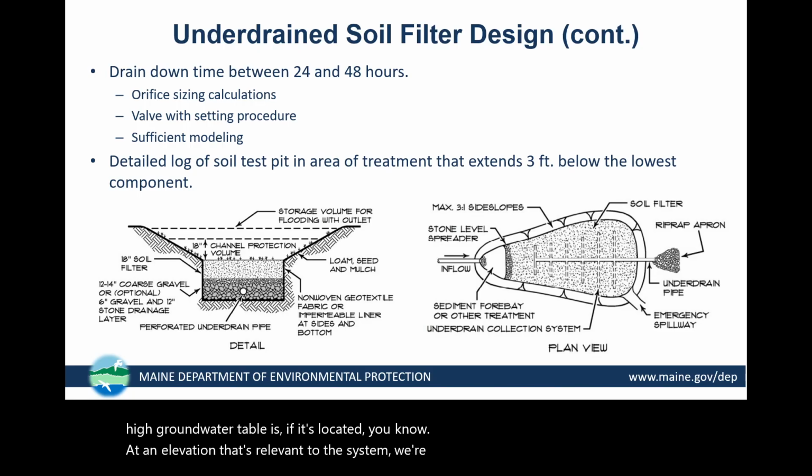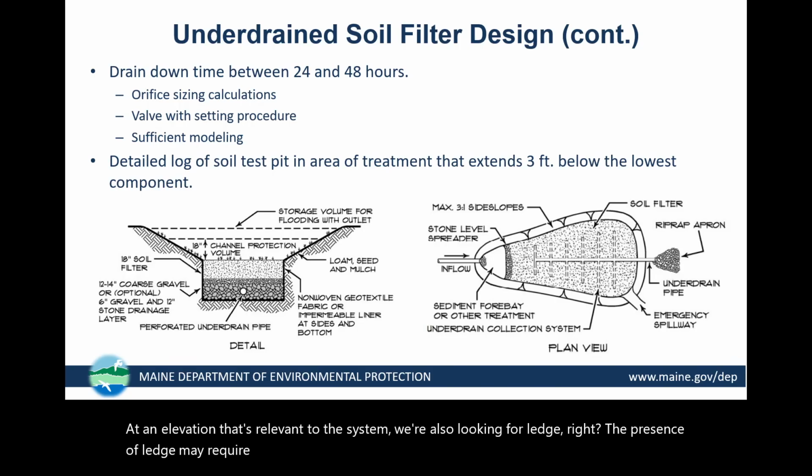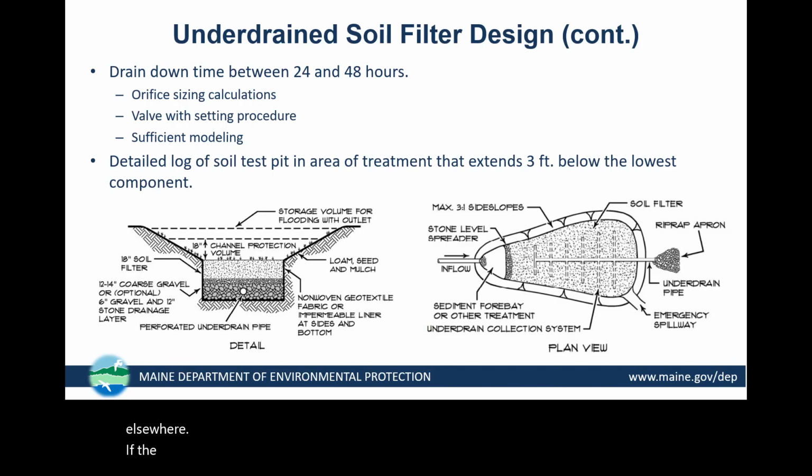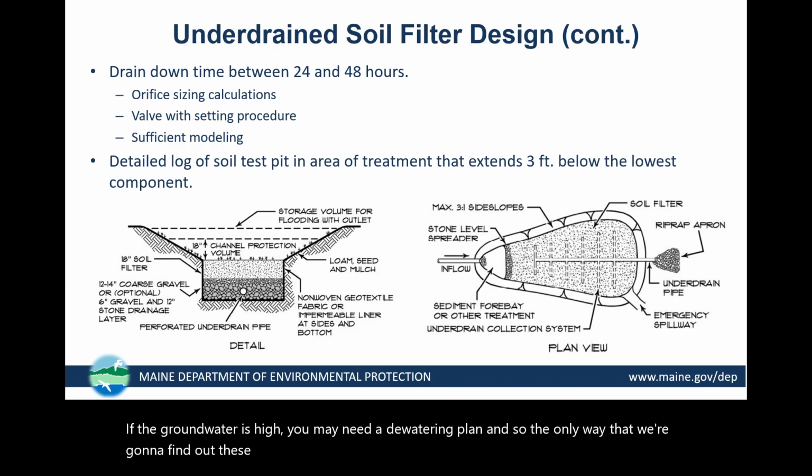We're also looking for ledge, right? The presence of ledge may require blasting for the system, or it may require you to move the system elsewhere. If the groundwater is high, you may need a dewatering plan. And so the only way that we're going to find out these details is with a soil test pit.